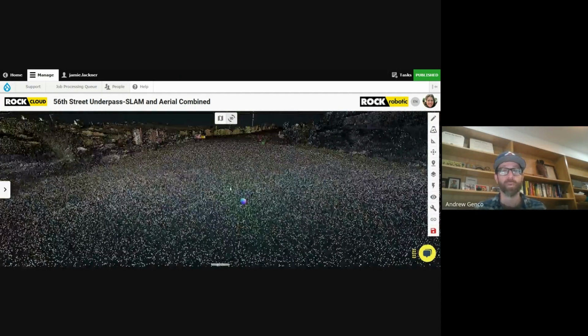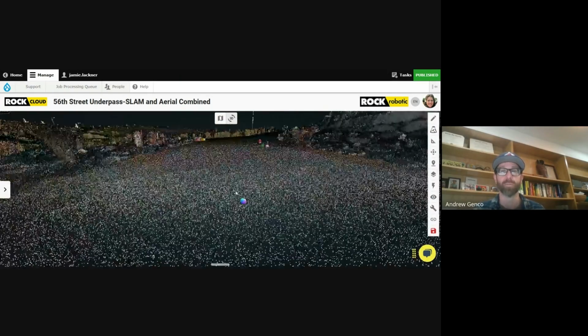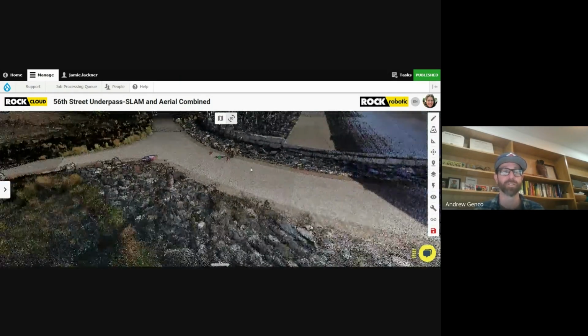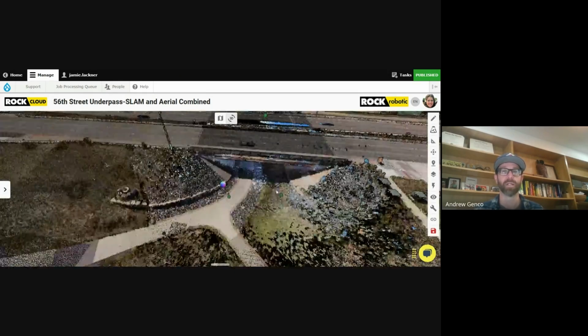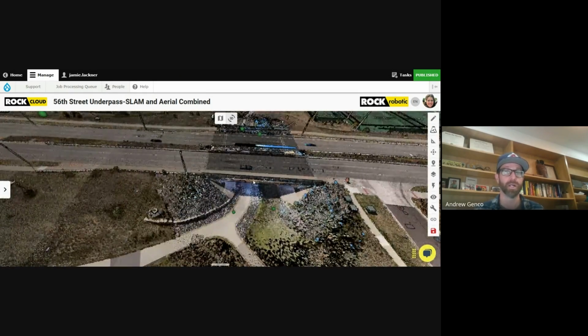So by following the steps above, both your airborne and SLAM data sets are going to be referenced to the same GCP network. And that's going to ensure that after processing and overlaying those 2 data sets, they are going to be accurately merged together.